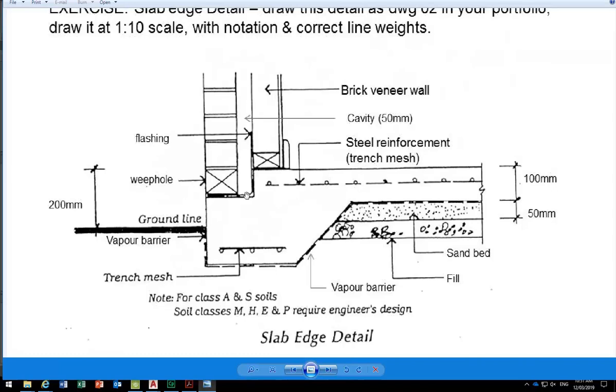It normally has mortar, but they just leave that out. So there's a gap you'll see in any brick wall every so often, where they leave the vertical perpendicular open for the water to come out.